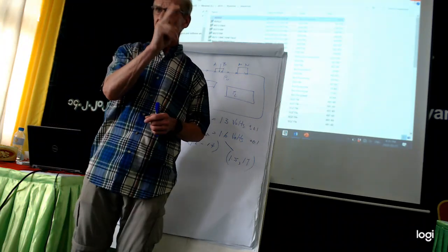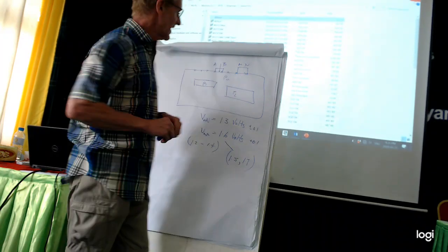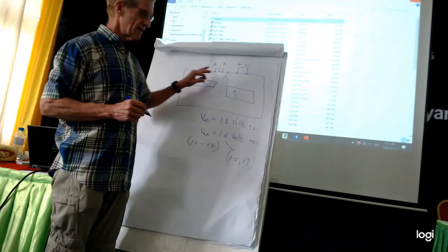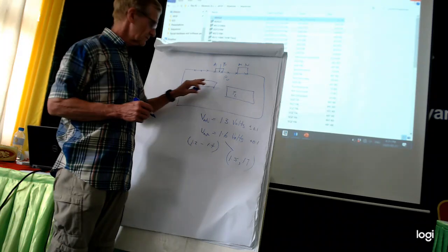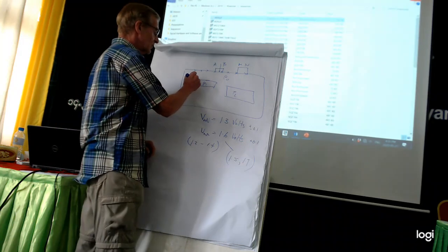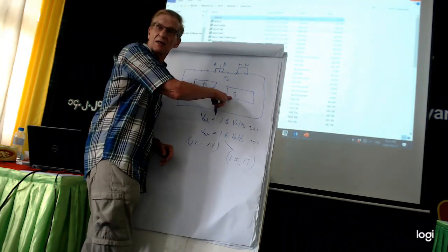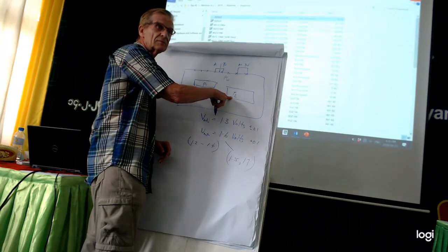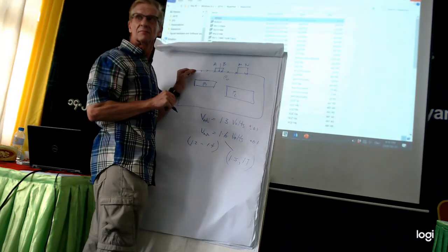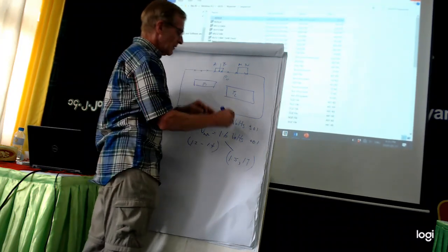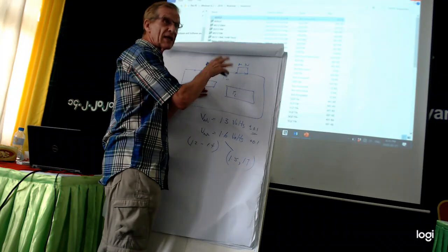There's another way of trying to quantify this, and that is to do a modeling of this and then do the inversion. Okay, so what we'll do is you want to see if a particular array can see these two blocks. So you design your survey, and then you add a little bit of noise, and then you go and you invert the data.